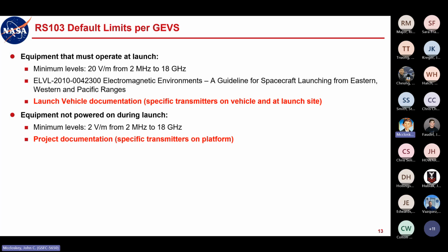Now, looking ahead a little bit, 2 volts per meter is a very low level to test to. The background levels that we generally sense with our electric field sensors are pretty close to that, somewhere between 1 and 1.5 volts per meter, or even pushing 2 volts per meter. You're probably bathing in pretty close to 2 volts per meter from just the lights in your office and anything else.